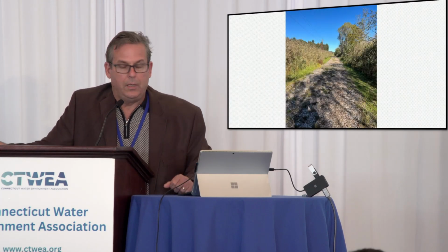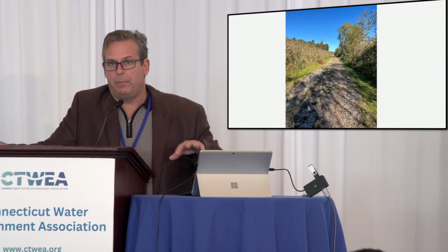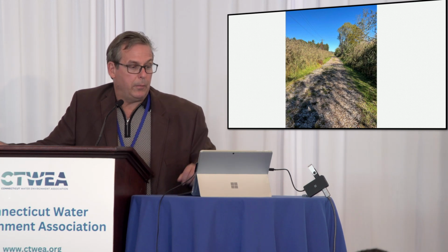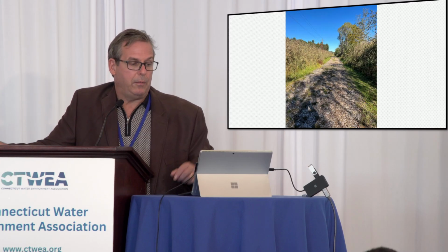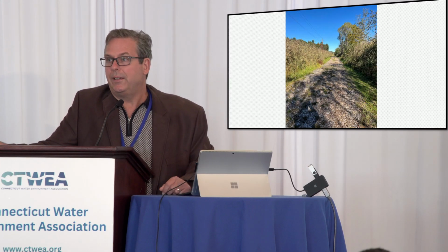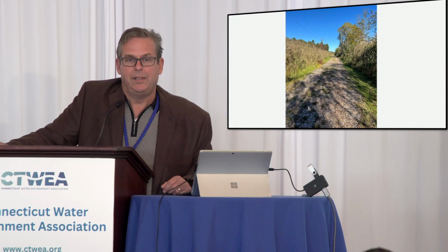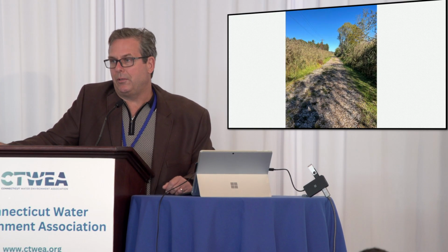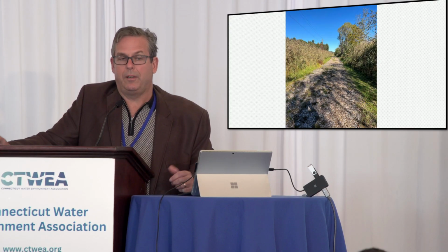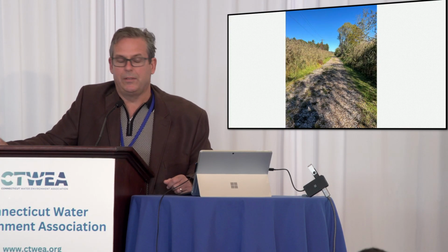So what my guys did, they went through a swamp where our main interceptor is, and so this is the swamp I'm telling you about where the beavers live. This is part of White Memorial Foundation. It's a popular hiking area. But we have like 10 manholes through this wetland area. So they went through there when it was pouring rain. They put the dye packs out. They came back in 20 minutes, and all the dye was going into the sewer line. So then we knew, okay, this is a problem for us.